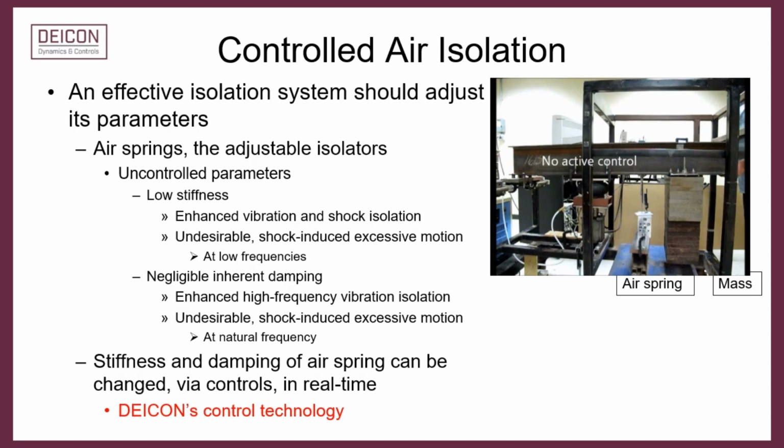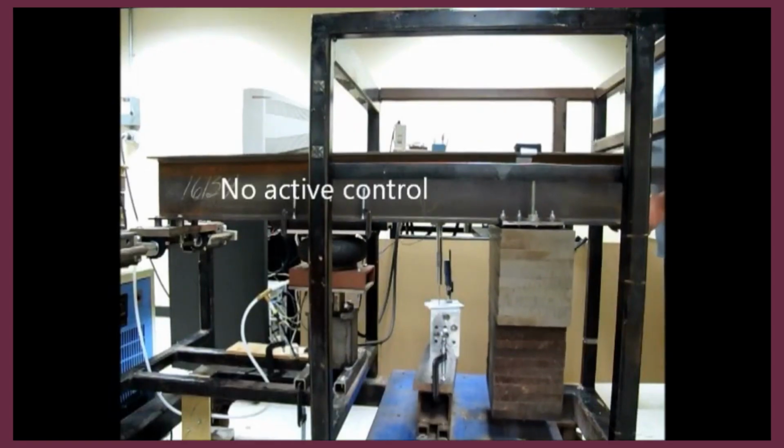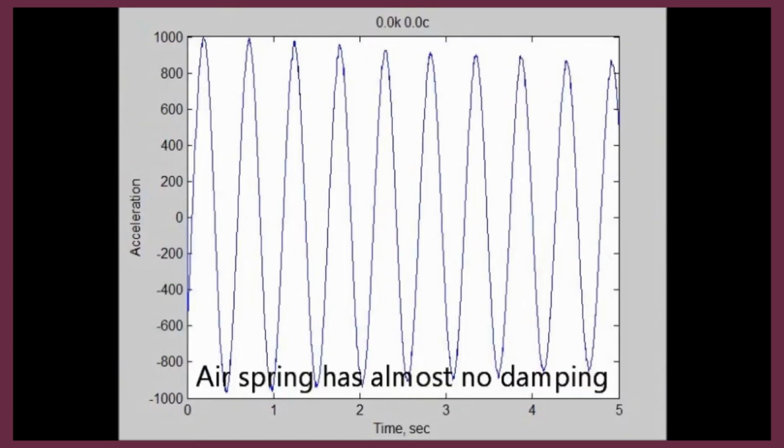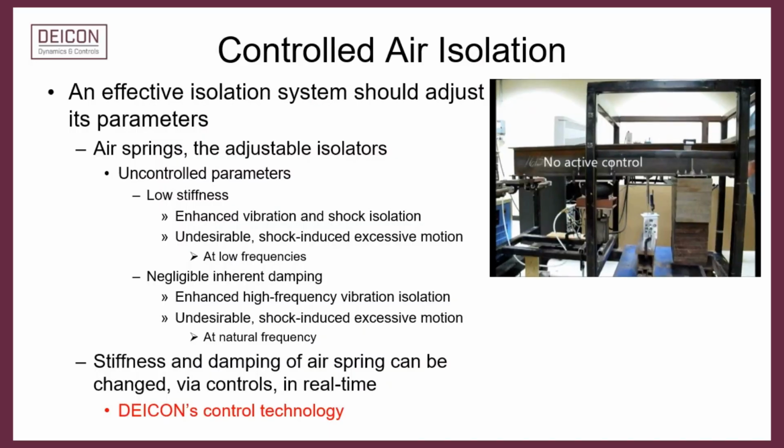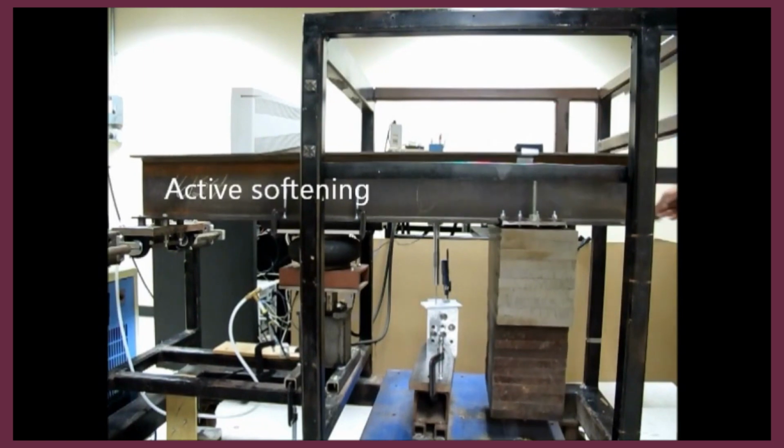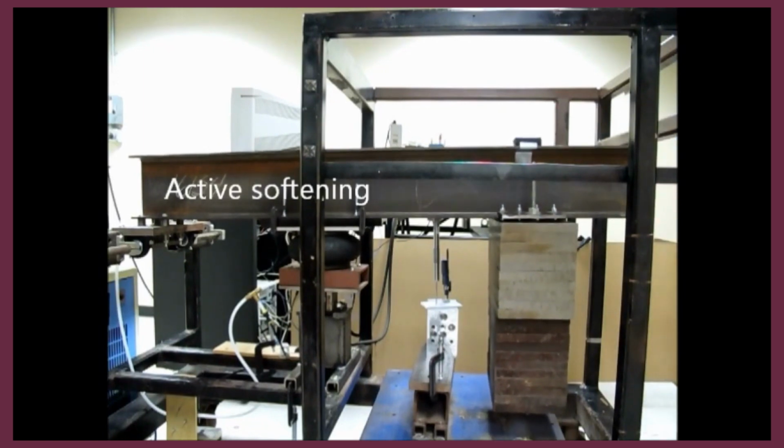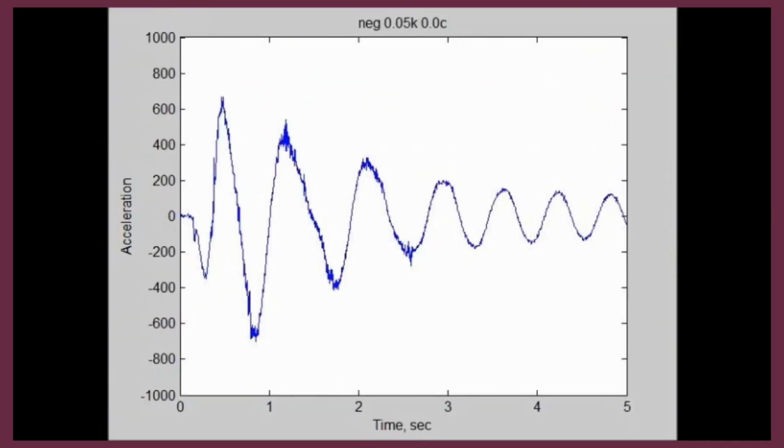The demo starts by having the system perturbed with the controller off. The response is almost undamped oscillatory motion with a frequency of 2 Hz. In the second run, the system is perturbed again with the controller set to lower the stiffness of the system. The slower oscillatory response is an indication of smaller stiffness and lower natural frequency.